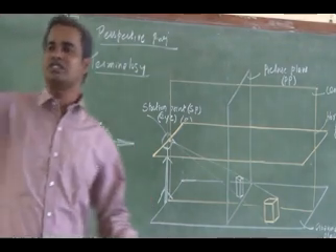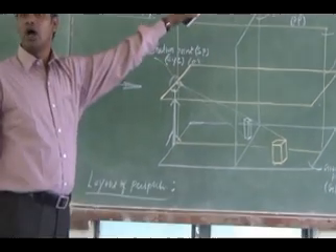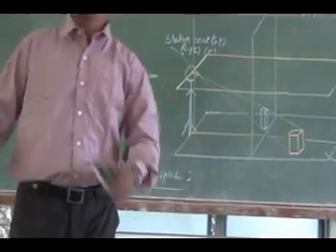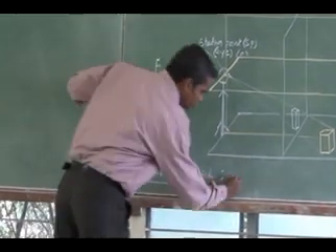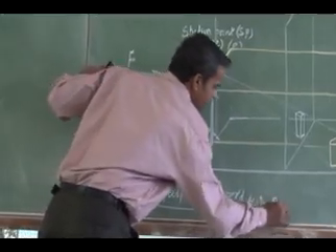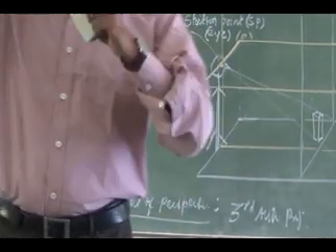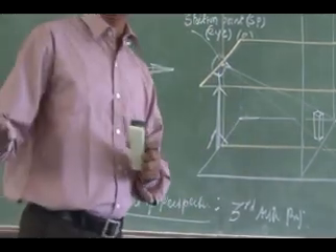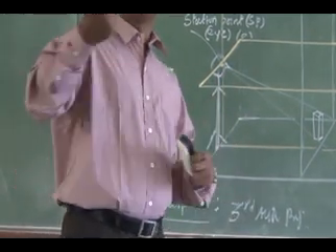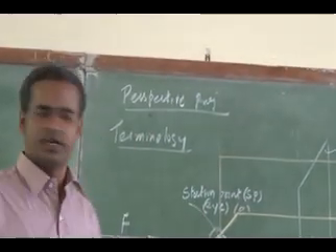So far we are using first angle projection. So the layout of the perspective is drawn using third angle projection, just for the easiness of constructing the perspective view. So we will be adopting the third angle projection to draw the layout alone, not the perspective view, right? Once the layout is drawn using third angle projection, the perspective view will be obtained easily, right?